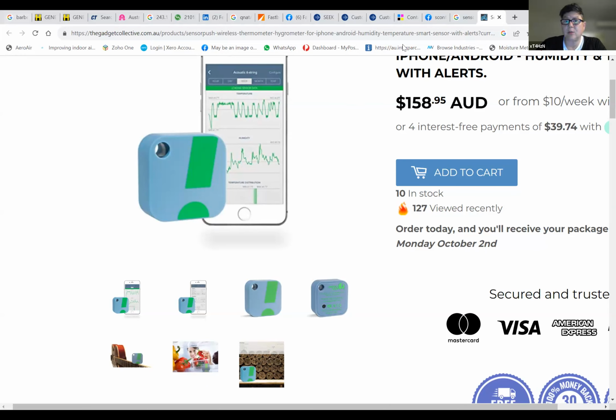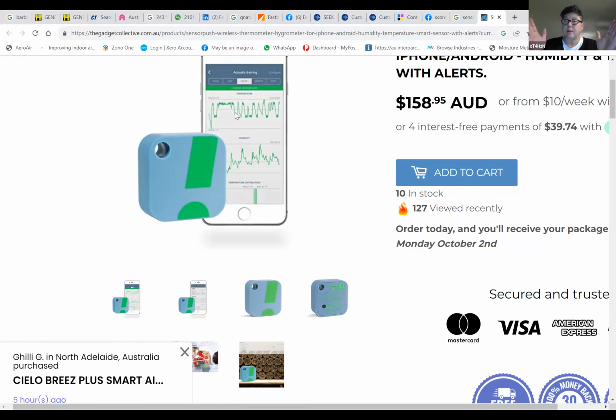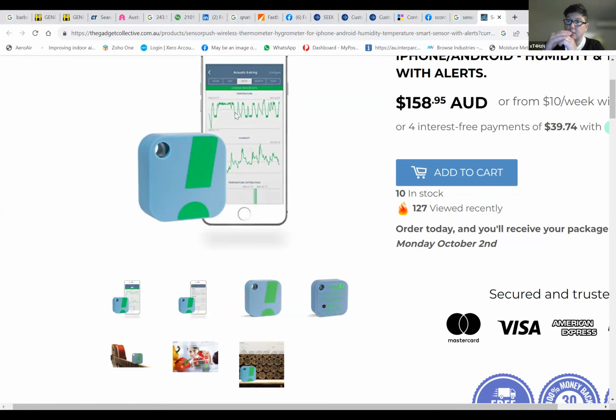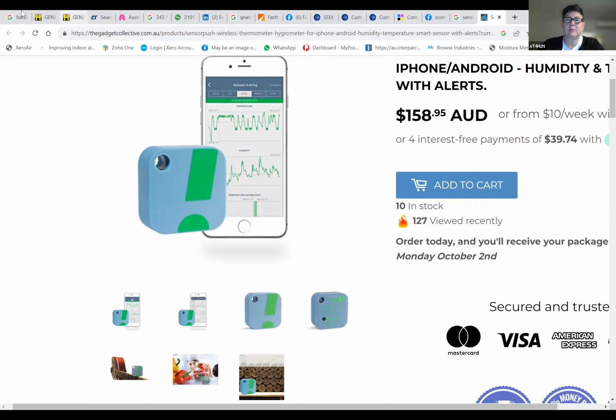They're what we call data loggers. They look at the trends, and with the trends, which are all these readings that they capture all the time that it's been placed here, you can actually look at it. You can go back to your customer and say, I looked at it between 8 and 9 o'clock at night. There was a high temperature difference there. Were you cooking at that time? Was there anything happening in that environment that caused the temperature and humidity to spike that much? Oh, I put my laundry out. Then that might be why. Okay.